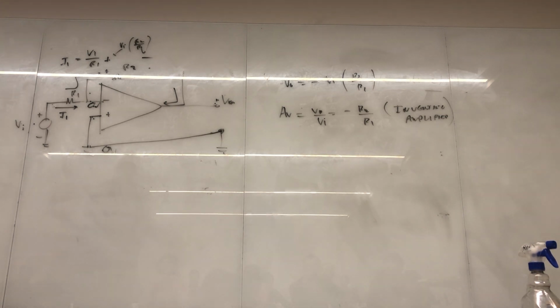For instance, a transducer like a microphone takes sonic vibrations to displace a cone. That has a little coil, and as the coil goes through around a magnet, it induces a current and voltage in that, and that is the thing that would be as the input to this. Then it has to be amplified.